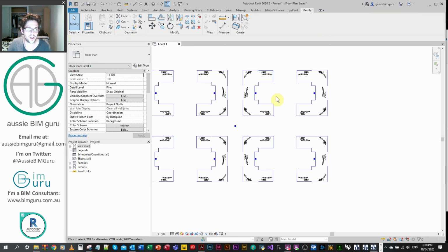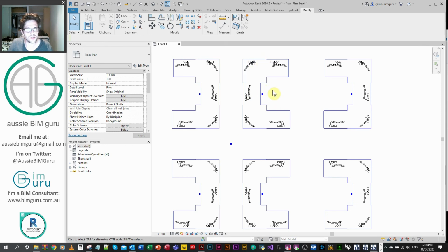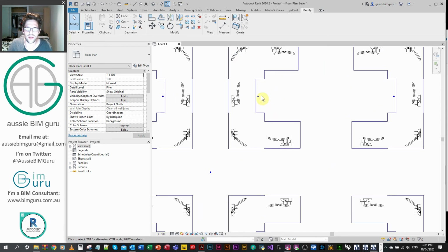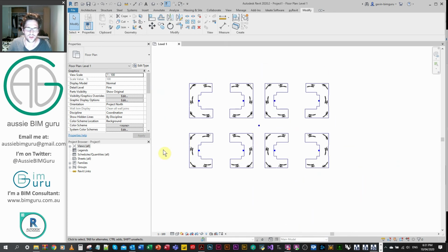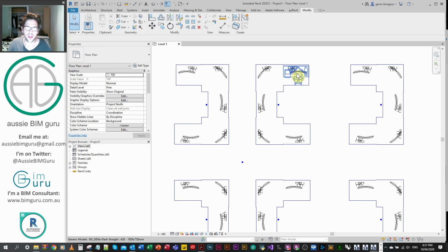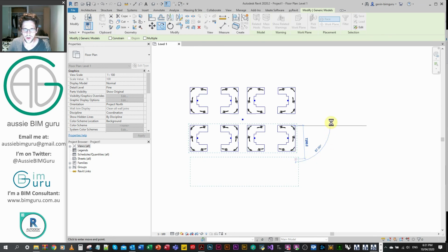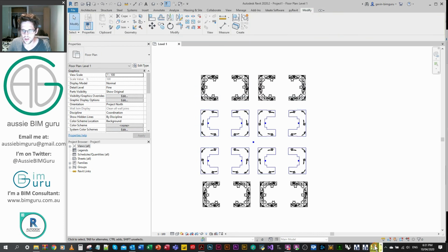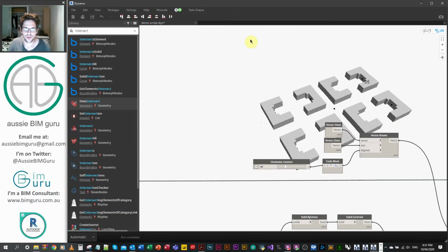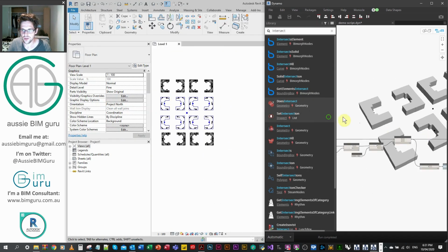And obviously if you kept working this workflow through, you could even apply sub-numbering to each of these little clusters. I won't do it here because you've seen the general concept, but you could work with sublists and apply a rotational workstation numbering rule as well, or you could just number the workstations in order regardless of whether they're in a cluster or not. So it's quite a powerful workflow, and as we add more things to the equation, our script should be able to handle more things. You will get to a certain point where maybe circular logic isn't the right way to handle a numbering convention, but in a lot of cases this is a suitable convention to use.